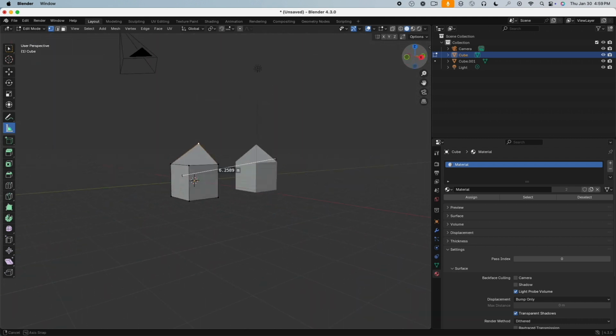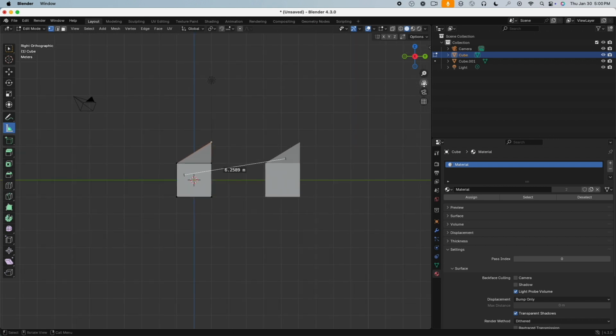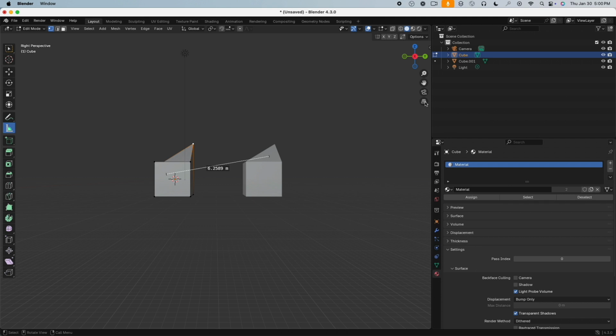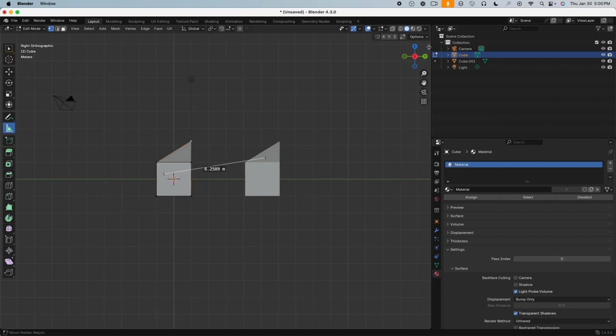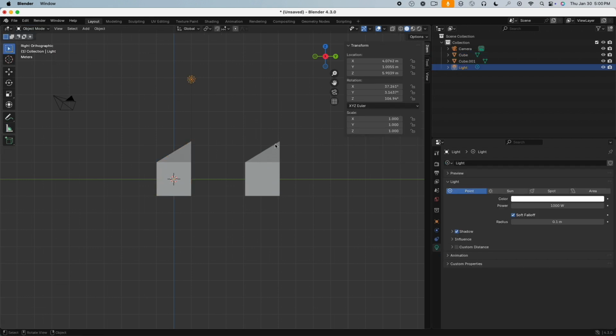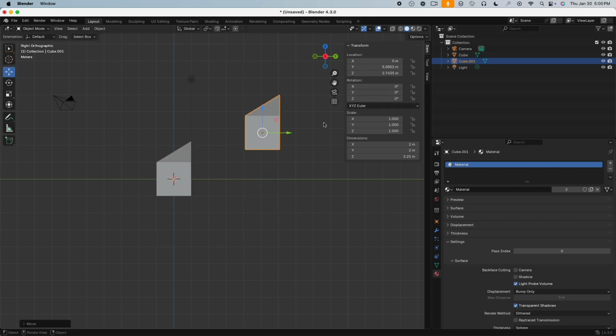On the right side here, you have the navigation tool for the different views. Also here, this is zoom in, pan, go into the camera or out, orthographic perspective view. With the N key, you can turn on this property panel. So if we're in object mode, then I see where all these objects are located. Here, I move this one up. You see these numbers change. If I rotate it, you see these numbers change. So I can overwrite everything, go back, and so forth.